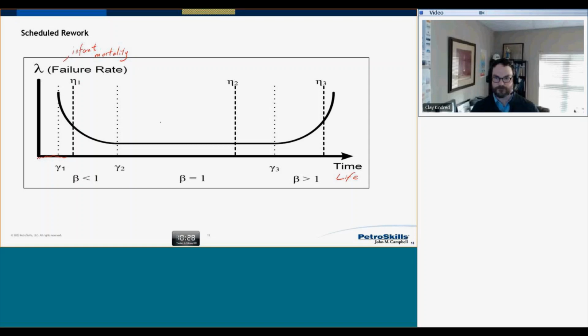This could be things like commissioning errors. We've installed bearings in there, but somebody forgot to put the lubrication in. There are maybe some problems with the instrumentation. Perhaps some of the cables got damaged. These are things generally that can be fixed quite easily. It might be a design error. Then you've got to go back to the drawing board.